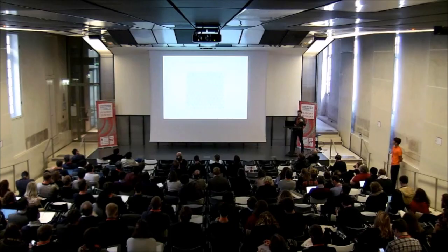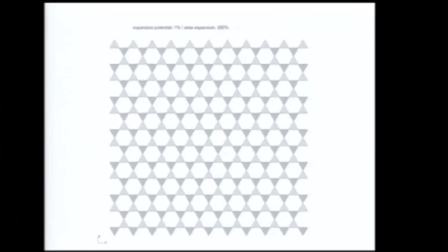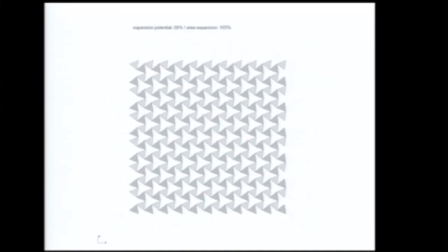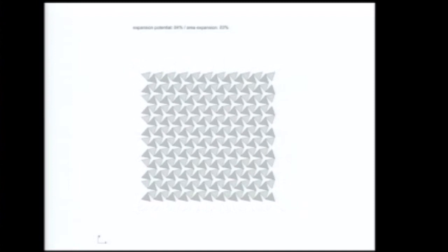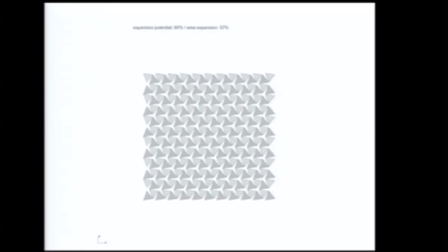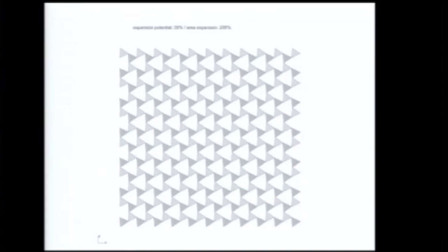One example, another one Riccardo showed us before, is an auxetic structure based on a triangular mesh, showing the process of stretching. Auxetic behavior on a macroscopic scale is facilitated by specific incisions, as you can see there, in the material, while keeping significant vertices connected, thus forming kinematic linkages.